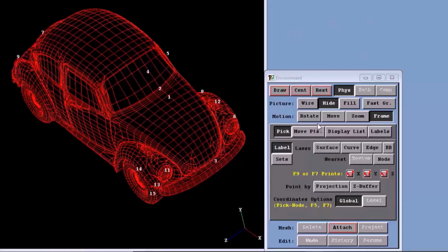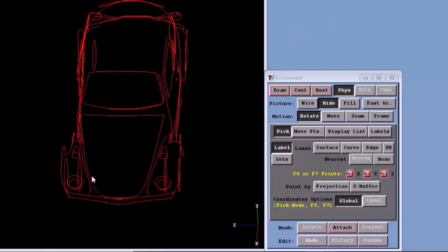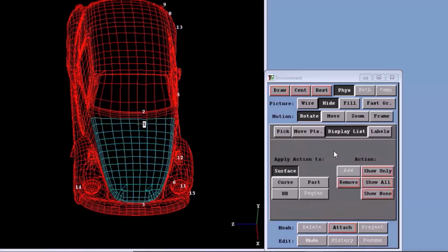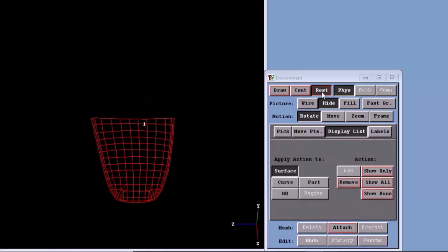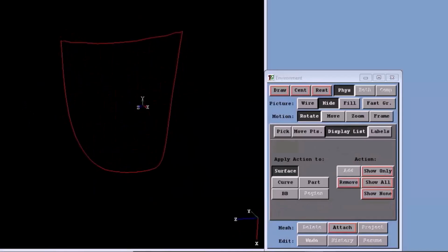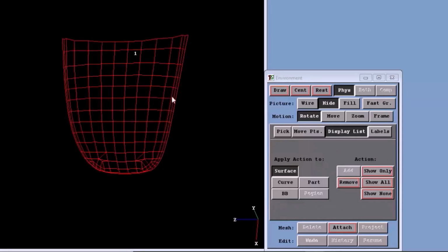Now, what I'm going to do is demonstrate to you how to use a polygon surface like one of these to build a mesh. And I'm going to take the easiest one, surface number 1. And I'll have it show only that one surface. Now I've shown you methods already on how to start building a mesh and projecting it to a surface. I'm going to show you another one. I'm going to put a shell mesh onto here.